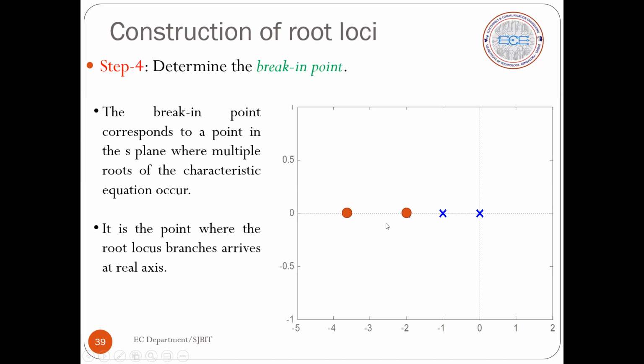You can please try out. All of you can give a try how to analyze the existence of root locus on the real axis. As we have discussed in the previous class, please apply that concept and try to calculate whether the root locus exists in this section or not. Since the angle condition is matching, I'll say that root locus exists between these two zeros.